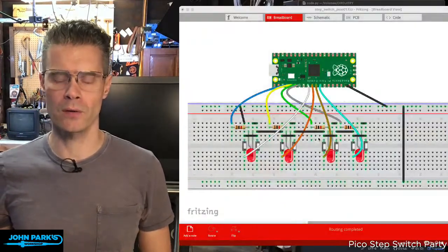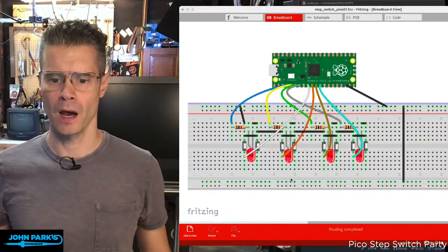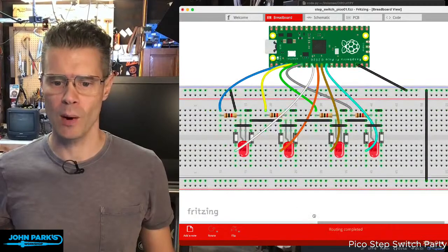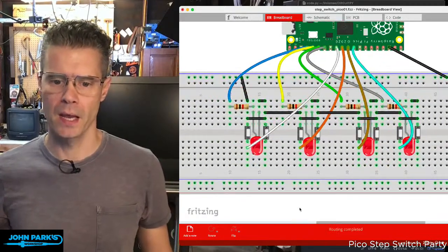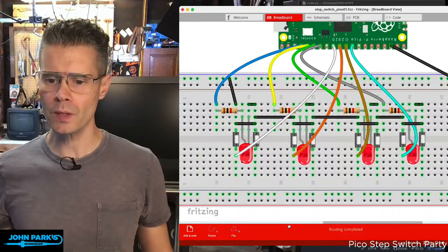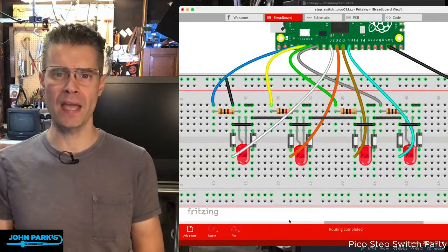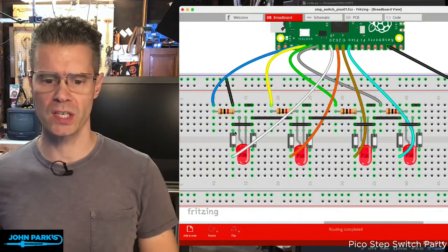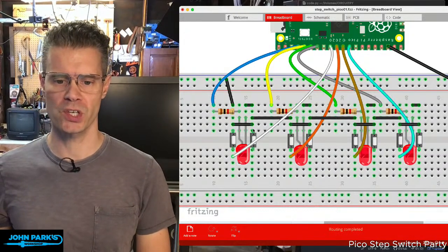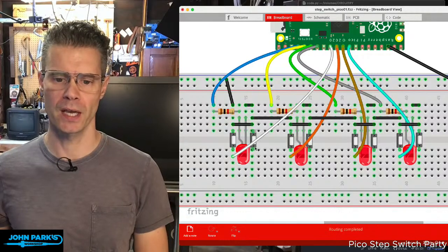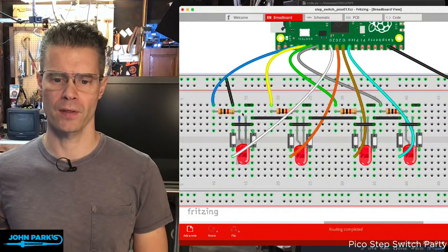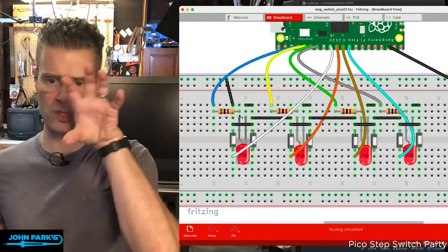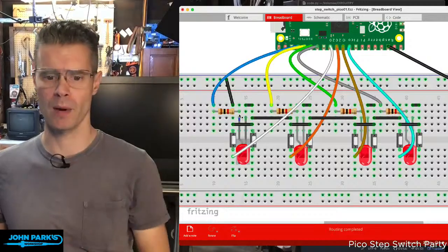If you look here, this is my Fritzing diagram of how I've arranged this. Oh, it doesn't want to route stuff, that's okay. I don't have a version of that made in Fritzing yet. We may end up doing one, but here you can see I'm essentially simulating this with a pair of switches that are in line with each other vertically, and then we have the LED flipped around so things are on the proper side when you flip the switch down. So this is looking down from the top, unlike that diagram that's from the bottom.